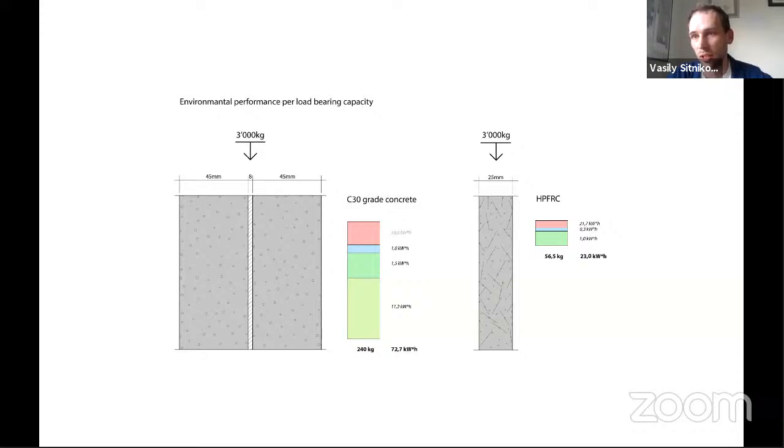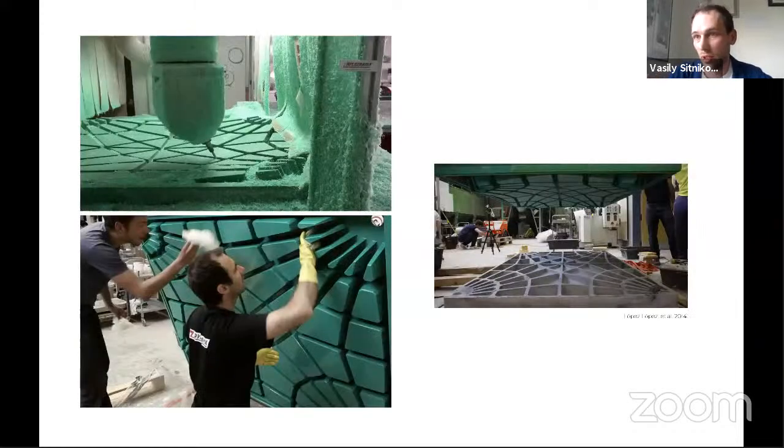However, a slender column like this would not fit any existing standards, would not be directly fabricatable on the existing infrastructure, because basically the tolerances for such a slender construction require to be much higher. Which leads to basically the second part of this talk, which is how does industry of concrete prepare to meet these structures, the new type, and basically reinventing the ways we build elements of concrete. Of course, with use of digital fabrication tools and new materials for the formwork and how it all sits together, right? So we can have clarifying questions at this point, just to make sure that I have not slammed through some of the topics.